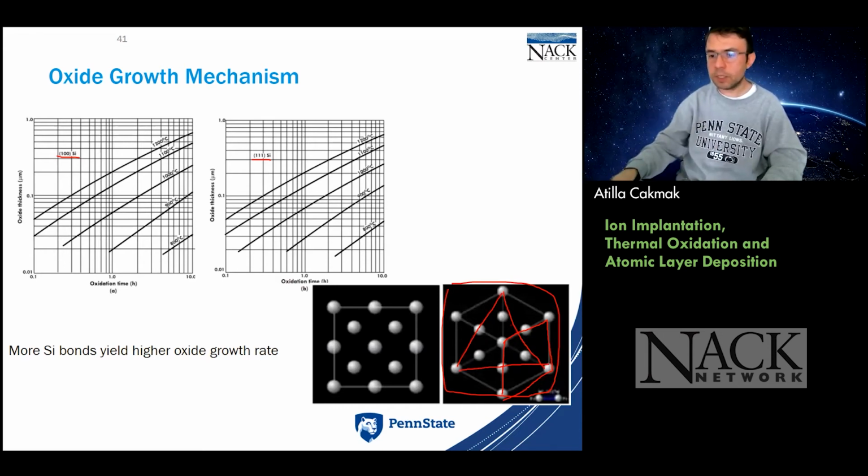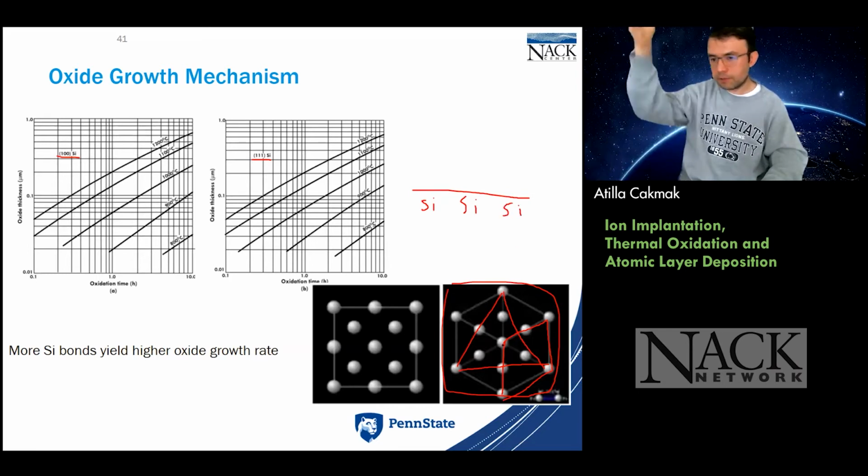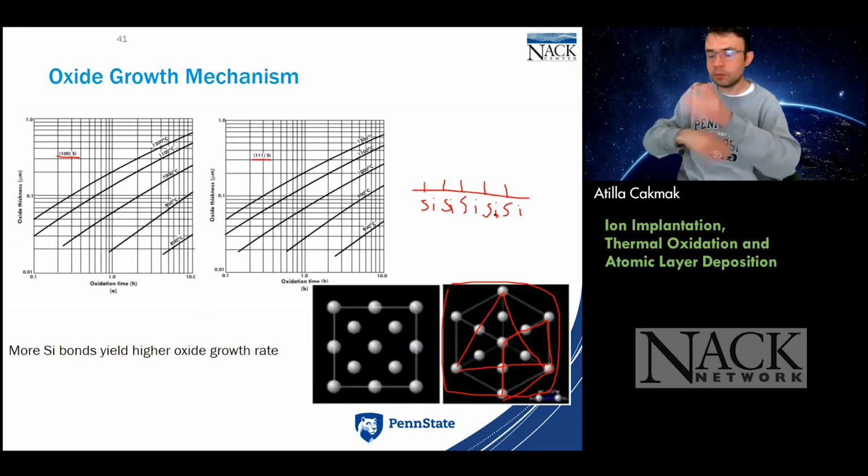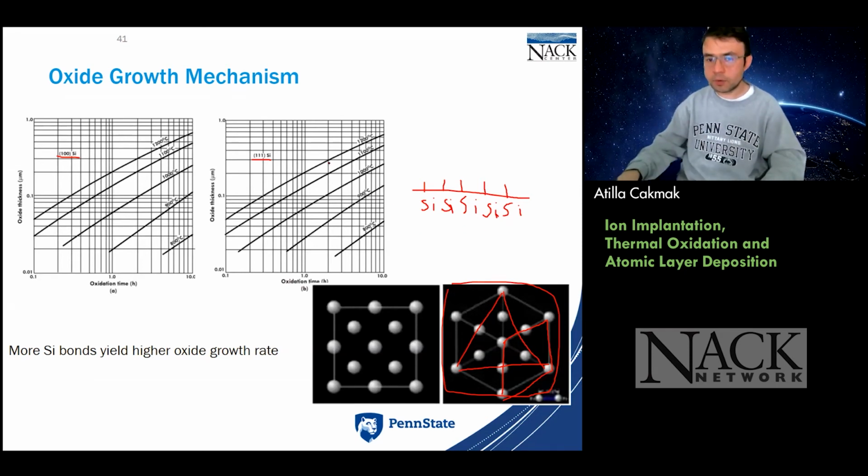Anyway, those are details, but the way that we cut it will bring different orientations, because the number of silicon atoms on the surface will be different based on the way we cut. If we cut it from the face, there will be fewer silicon atoms on the surface. But if we cut it diagonally, there will be additional silicon atoms that we just cut. What does that mean? They will bring in more possibility of chemistry, more bonds there. That means more chemistry, quicker, rapid growth. So we will grow the material quicker. So that means 111 will grow quicker.